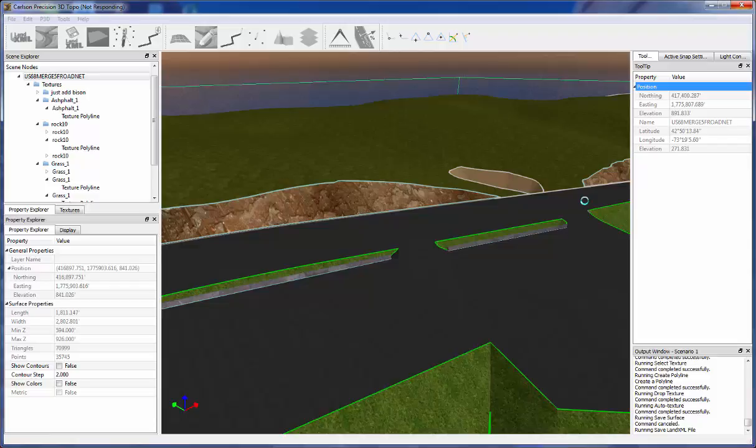And again, any other software that supports LandXML 2.0, all the texture images and everything that you see here is embedded within that LandXML file itself, and it does not overly bloat the file size, because we do compress and then use a hex encoding to actually embed that binary data directly in the LandXML data structure. So it is fully portable to any other software without requiring additional files and so forth.